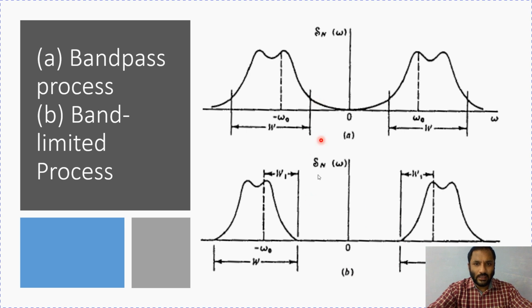Now this is the characteristic of a band limited process, because normally it is a simplification of this band pass process, because in real signals, most of the power is distributed around the carrier, in this bandwidth W. But outside this bandwidth, typically, let's say 5% of that power can be cut off, can be made equal to 0, so that we can save these frequencies for another channel.